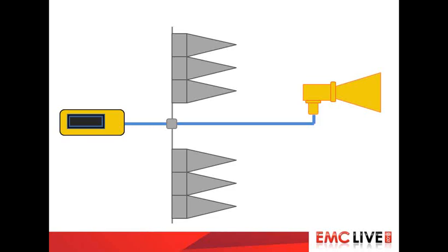And this more schematic sort of drawn picture shows you the block on the left-hand side is supposed to represent an amplifier. On the right, there's the antenna we've been using all the time. The antenna's inside the chamber, as shown by the pyramidal absorbers there. And the cable goes via a bulkhead and in the chamber. And I think reasonable numbers would be 3 meters from the amplifier to the bulkhead and another 5 meters from the bulkhead to the antenna, which will be on the tripod.